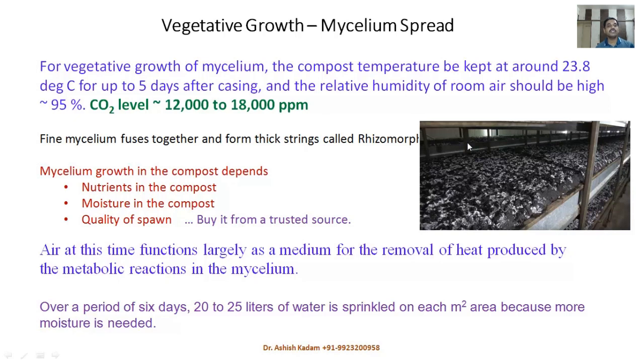But we need to remember that air exchange between room air and outside air will happen only if the room air has more pressure than the outside air. So just having a small window does not mean that your CO2 level will get maintained. This is, I would say, a misunderstanding, that providing a small opening means you are taking care of the CO2 level. That is not the correct science that we need to understand.